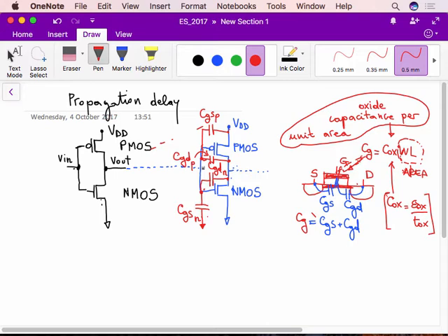Okay? So, and we are going to compute exactly that time. In addition to that, there is a wire here, which is a metal line, that of course has a capacitance with respect to the external world. So we need to represent this capacitance as a capacitance of the wire. Okay, this W is the wire capacitance, because of course there's a line, a metal line, between one inverter and the other, and in general between the output of one gate and the input of the following gate.